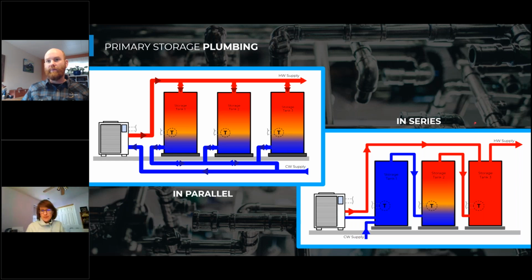But I'm just opening this up to all of us, that there are two primary ways to connect our storage tanks. And if we've been operating in the gas water heating world, we're probably fairly used to seeing them connected in parallel, those gas water heaters, but not in series. And so we might once again be taking a little bit of a different design approach to really benefit the operational range of that heat pump water heater with that in-series connection.